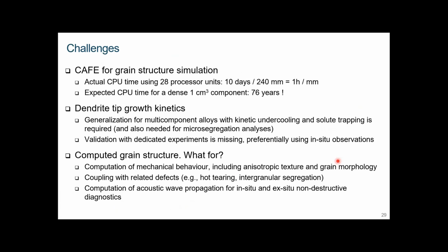Okay, I want to conclude very quickly. I see I am out of time very soon. So, yes, you can do CAFE simulation of grain structure. One of the challenges though is the CPU time. Actually, using 28 processors, it took about 1 hour for 1 millimeter.